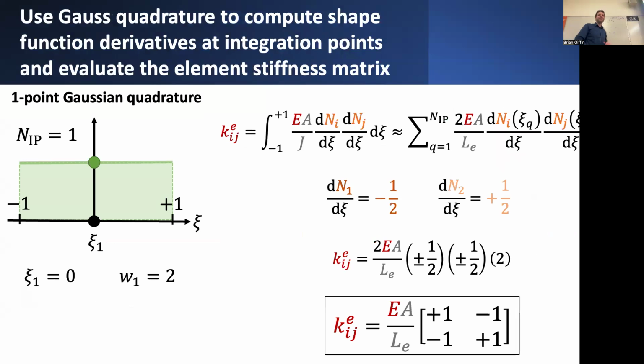And now I can use my integration formulas, my trusty Gaussian integration rules, which in the particular case of this simple one-dimensional finite element that just has a linear interpolation of nodal displacement using these simple shape functions, I notice that really these resulting expressions for the derivatives of n1 and n2 with respect to c are just constant values.